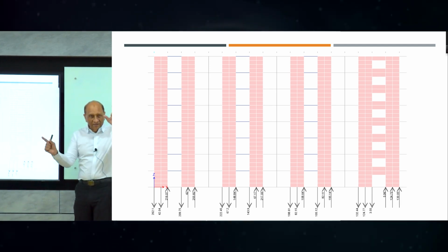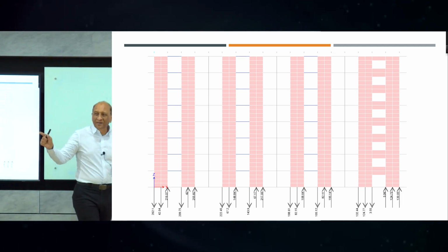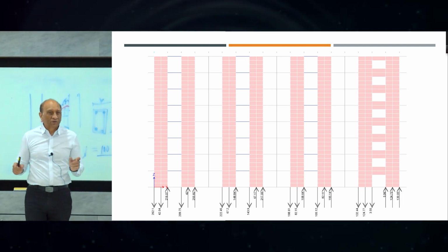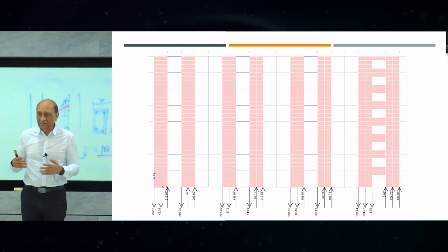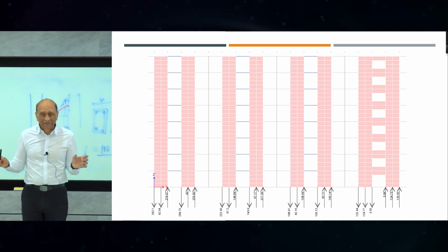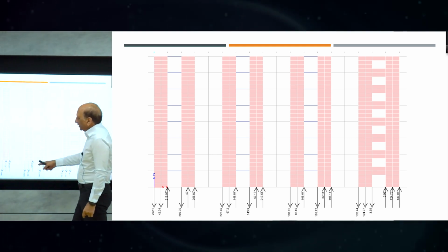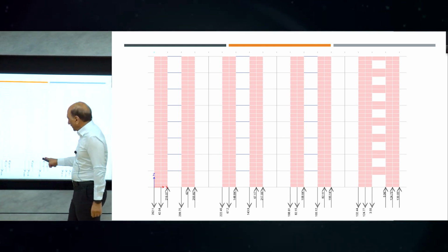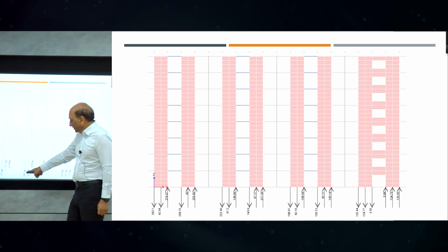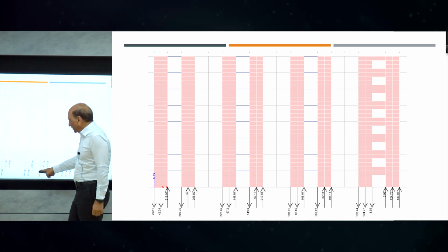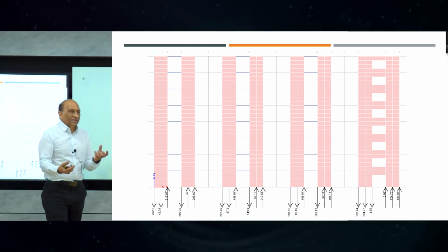That means they are completely connected now as one part of the single structure. They have been connected to behave as one. Instead of two separate walls, they're completely coupled. So here they're fully coupled. Here they are not coupled. Here they are almost coupled, right? So you can see the coupling effect from the change in the axial forces and change in the foundation load.